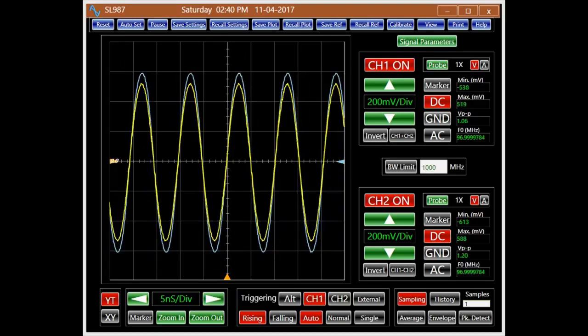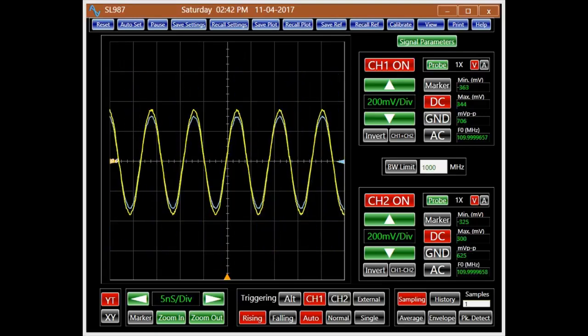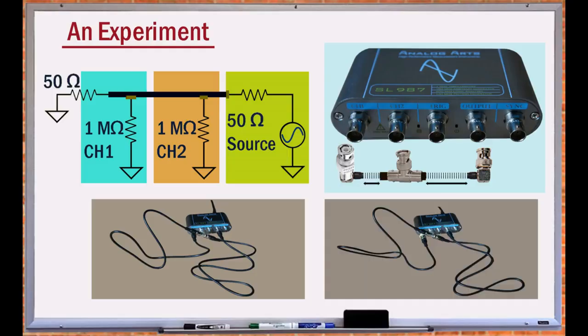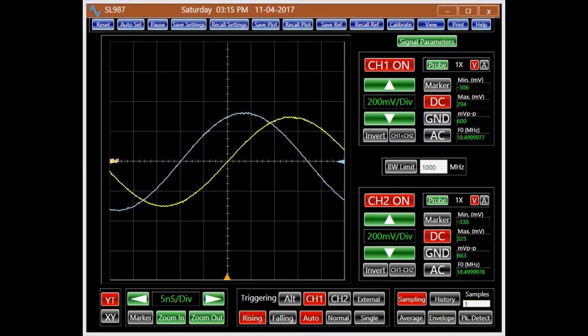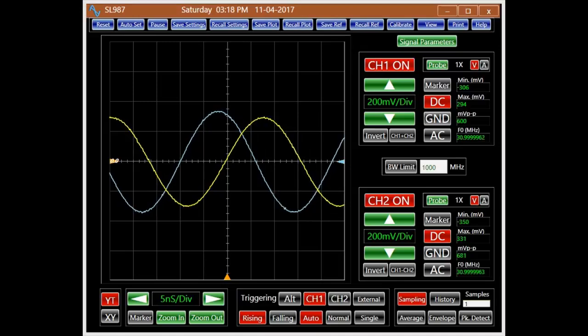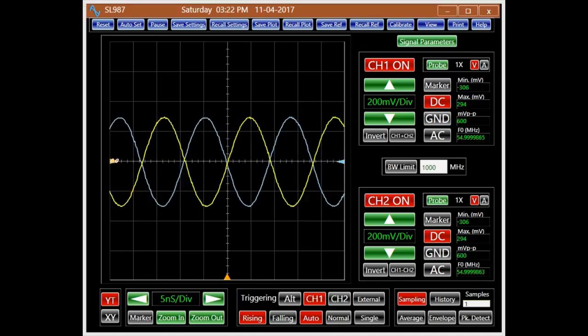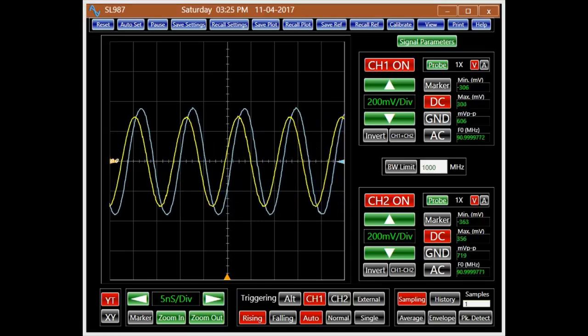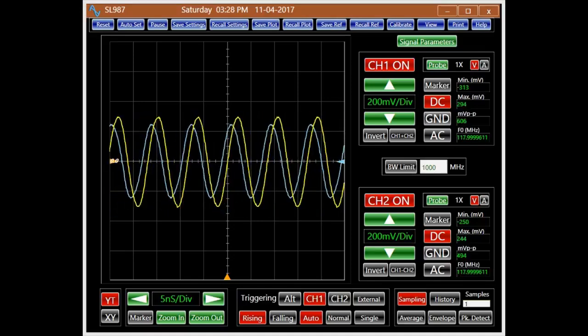Increasing the signal frequency affects reflection, and changes the amplitude of the resultant wave. With a 50 ohm termination, the effect of reflection becomes insignificant. The small variation of the signal at the connector is due to the slight impedance mismatch between the cables, source, load, and BNC connectors.